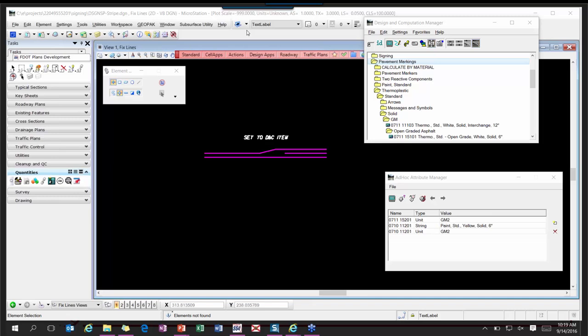With the permanent markings, you've got to wait 14 days before placing them. So the temporary marking is the paint, and it's covered under 71090. When you calculate all of these items for the thermoplastic, if you're supposed to have paint, I'm quantifying the paint for you, okay? If you realize that it didn't calculate the paint and it's questionable and you're not sure, contact either me, Chester Henson. One of us can answer your question and verify, yes, it's doing what it's supposed to, or no, it's not.